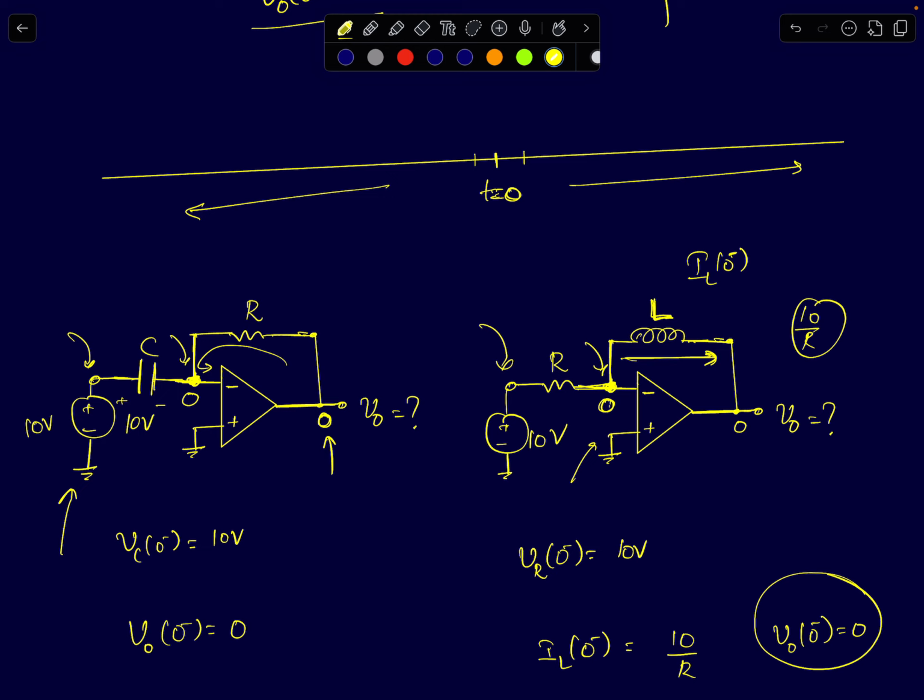But when you're analyzing op amp based integrator circuits, whether built using inductors or capacitors, you cannot clearly say what the steady state output voltage will be. For that, you need more information: either the initial voltage across the capacitor, or the steady state current flowing through the inductor should be known to you. If you know that, then you can precisely predict the steady state output voltage.